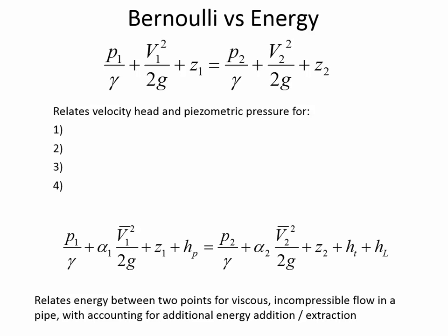But now H sub T, T stands for turbine. In the same way that P stands for pump, they are either adding or subtracting energy, and as expressed in these terms, it has units of length. So pump head is how many meters of energy is being added. We express the energy in terms of a height. That seems weird, but it's not weird, so don't say it's weird. It's like pressure can be expressed in terms of a height as well.